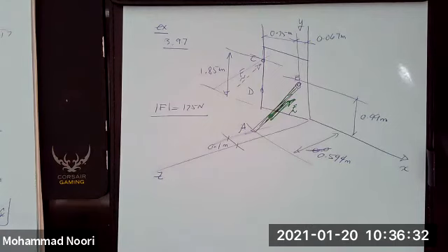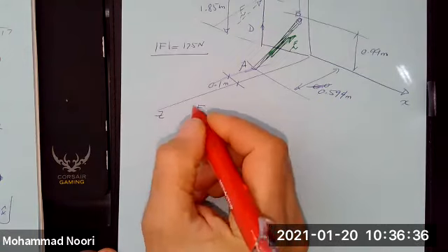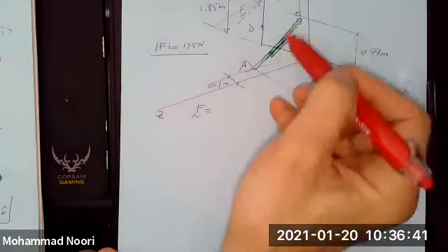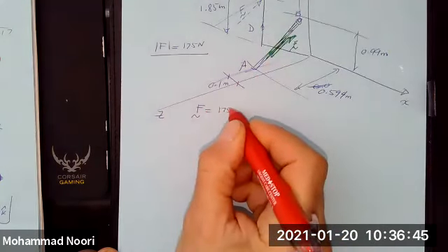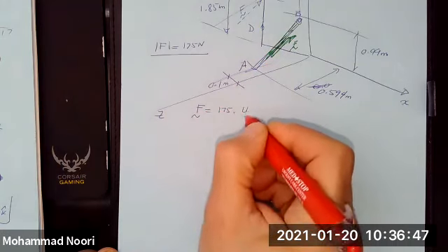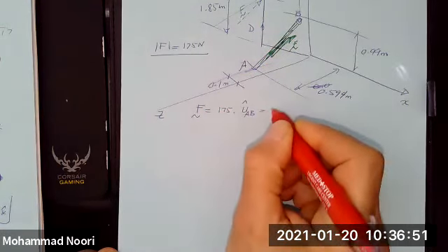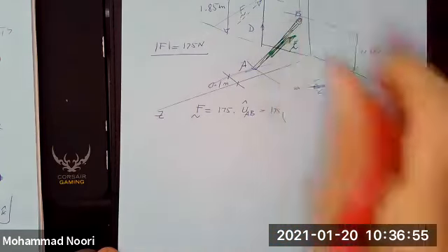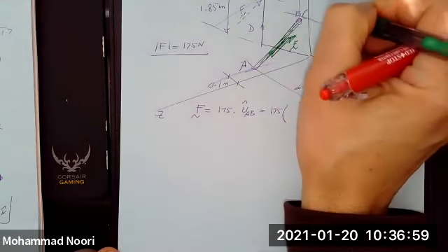All right. So first of all, what is the vector equation for this force? Because I need that to find its moment about point C. That would be the magnitude of that times the unit vector of AB. What is the unit vector of AB? Let me write down the coordinates of these points.